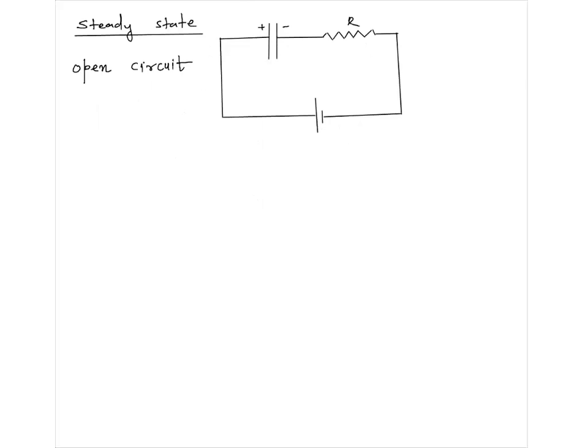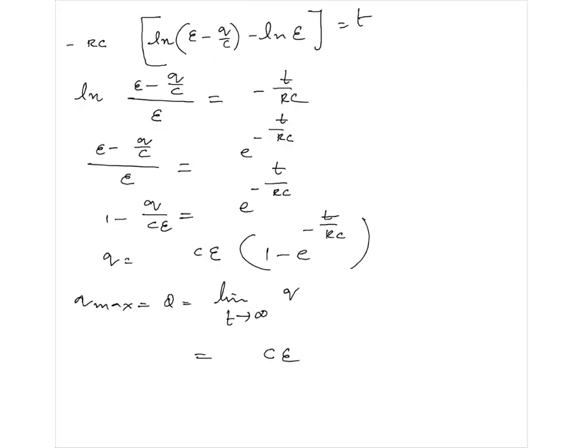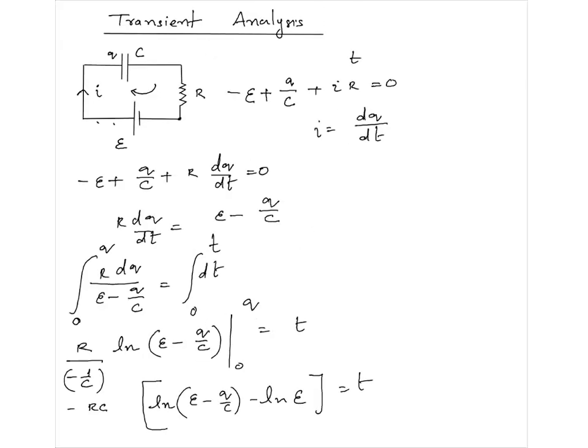Look at this circuit. Now, if I is E by R, what does it mean? It means circuit does not see capacitor there. Ohm's law is working directly, I equal to E by R. You don't apply Ohm's law normally when you have capacitors. It's as if C is not there. As if in place of C it were a straight wire. That's how Ohm's law is working, I equal to E by R.